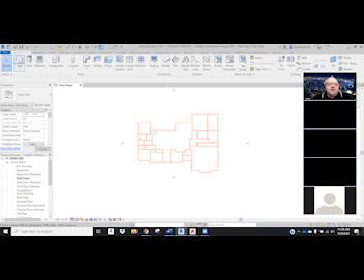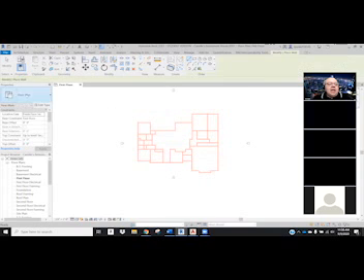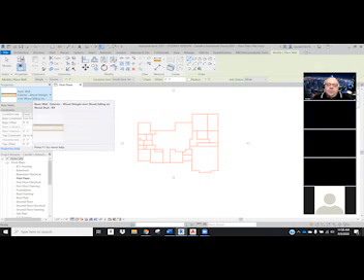First thing we're gonna do is go to the architecture tab and click on the wall tool. And I'm gonna cancel that. Now once we get that, it's gonna bring up a preliminary wall. It will probably be different for each of you, depending on what you've been doing in your plan. That little small practice one we can go ahead and get rid of. We're gonna trace off our exterior walls and create some.